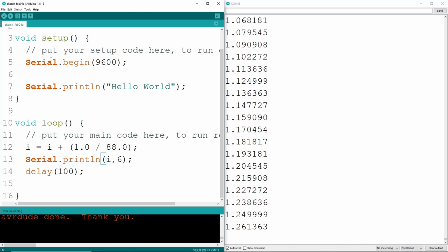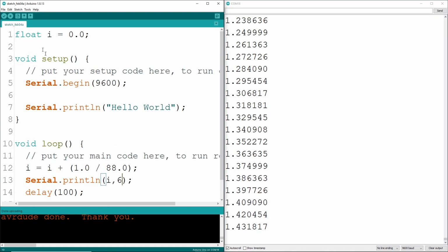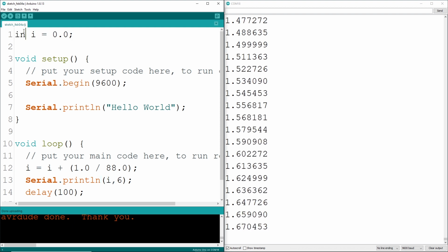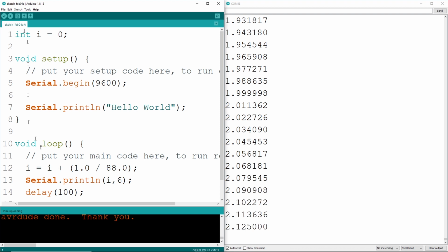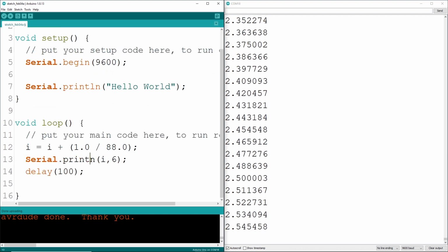Let's output the hex and binary equivalent to integers. This seems like busy work, but as you get more advanced in programming Arduinos, knowing hex and decimal values will be pretty useful. Change your i back to an int and change the incrementing line. This time I'll shortcut the code with simply i++. This example code will print a complex string of data with variables sprinkled throughout.